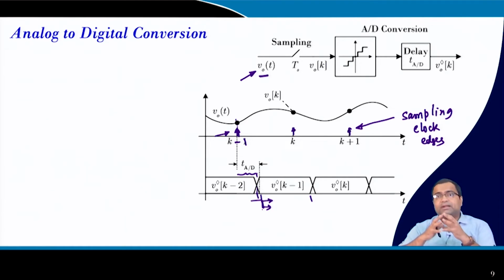So there are different types of ADC architecture I am not going to discuss, but the conversion time can vary from ADC to ADC, and there are different ways of getting the digital signal. But we are concerned about the delay, even though the ADC can sample, because there are two terms that come into the picture in ADC. One is called throughput.